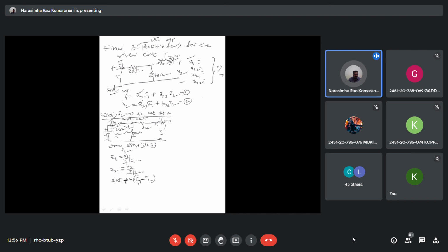is it I1 minus or plus? See the current direction. Yes, sir. ఇది ఈ direction లో ఉంది కదమ్మా, అందుకని I1 plus I2 is equal to next. That is not minus, అన్న plus, ఎందుకంటే if you see here I1 and I2 in the same direction, so therefore you will get the 40 into I1 plus I2 is equal to, yes, complete it, V1.